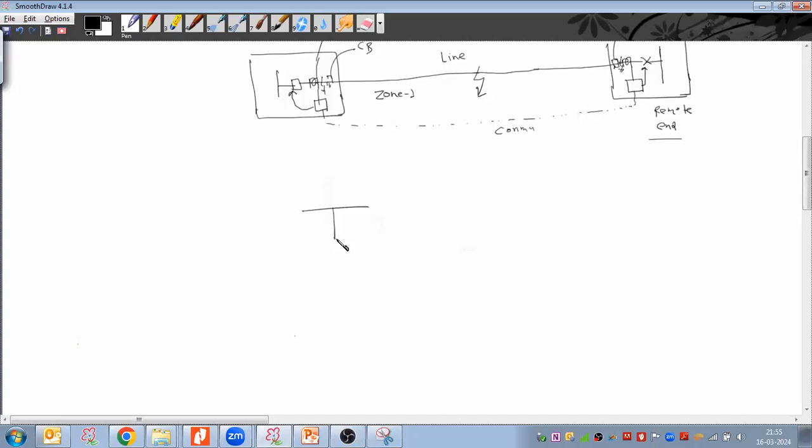busbar and the disconnector there is enough adequate space available. But when it comes to the GIS, this is very compact equipment placing, and the disconnectors are exposed to VFTO, very fast transient overvoltage.